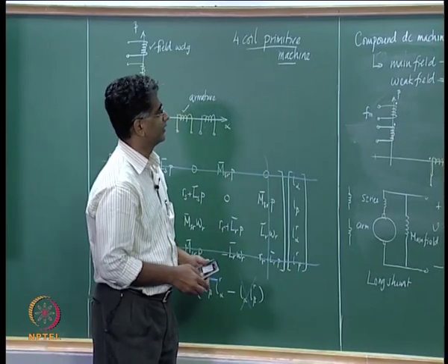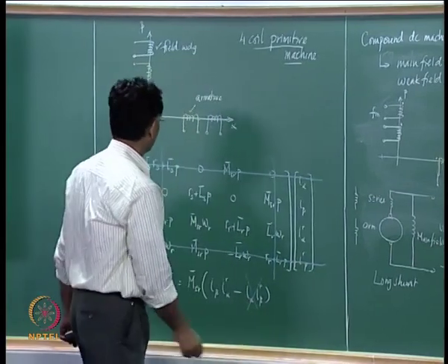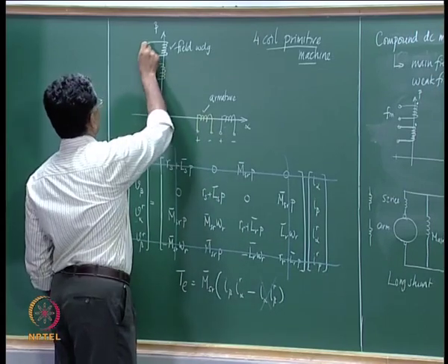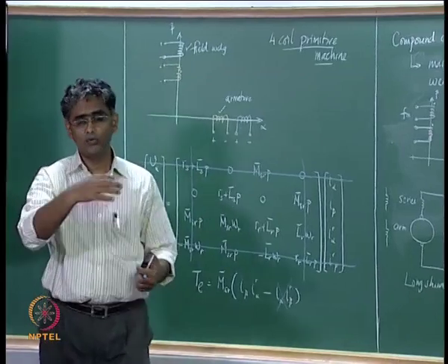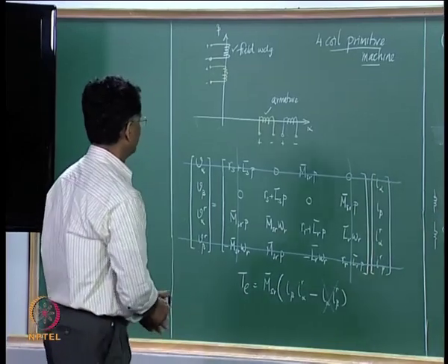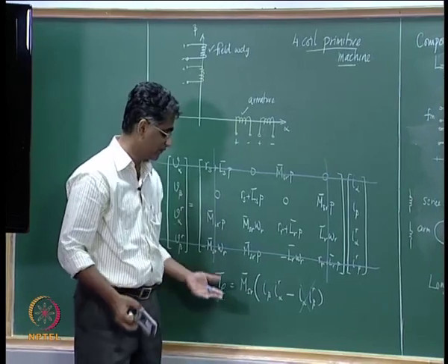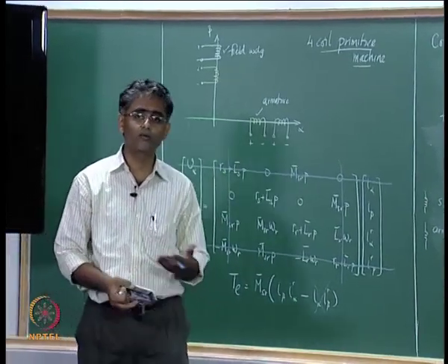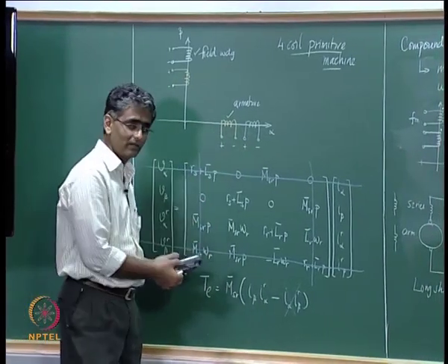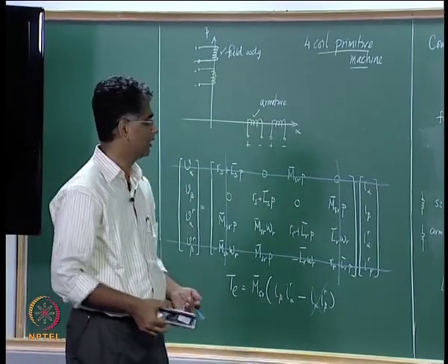In these DC machine expressions, we have not a priori made any assumptions on the nature of the voltage that you are applying here. They may be steady DC, varying DC, or DC that is switched on and switched off. In any manner that you may apply, these equations still hold. And for the mechanical expressions, we have not again made any assumption on what kind of loading is there. So, these are fairly general equations applicable for any sort of study on the DC machine behavior.